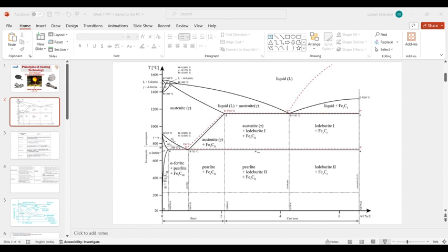This is obviously wrong. Then if we talk about manganese, then manganese provides ductility and strength to the system. This also stabilizes our austenite phase. Then coming to tungsten, that imparts brittle properties in steel. Generally we don't go with tungsten in stainless steel as alloying element. But if we are going with tungsten, that will increase the hardness of the stainless steel.